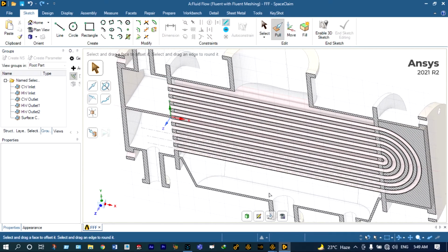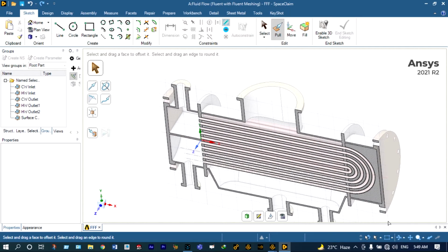You can see here, from here you can understand very clearly. Cold water will be passing from here, and it will be passing through these small U-tubes, and finally at the end it will be bent, and it is coming out from this opening. So this is the opening of cold fresh water, and this is the exit of cold fresh water, and this is the entry of exhaust from the turbine, and from this exhaust we will be providing hot water at 100 degrees centigrade. This exhaust water will be utilized to heat this fresh water which is coming from this inlet, right?